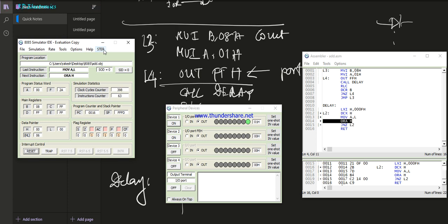Now see that return is executed and it comes back to RLC. After RLC, yes, there is some problem. What is the problem? The accumulator is 0 0, because after this subroutine the accumulator is 0. That's why this is a debugging process to solve the error in a programming. This is a very crucial method.